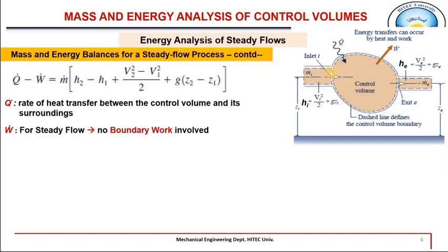Therefore, the fluid properties at an inlet or exit will remain the same during the whole process. They can be different at different openings or outlets, but at one particular opening, these thermodynamic properties do not change with respect to time. So what we are saying is that no properties change at the boundaries with respect to time. This means that boundary work cannot be done.